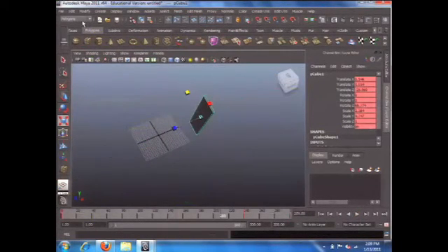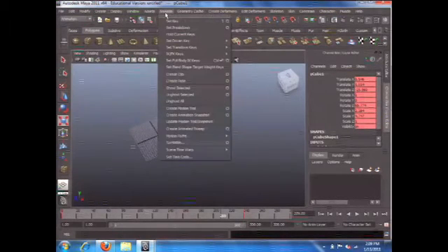Then this is a really cool thing. I can switch the animation to the animation group. So here you can see a bunch of new tools available. I'm going to do animation, create animation snapshot. This is a tool you can use to duplicate objects along the timeline. So I'm going to check the setting box, animation snapshot.